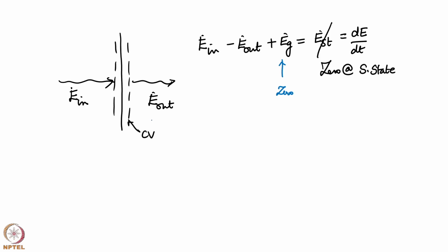How is heat coming in? This is the surface of the brick wall. There is an inner surface, there is an outer surface. Through this, energy is coming from Ts1 to surface S2 by conduction. So, the mechanism is conduction here, and energy is going out by convection. So, E dot in is equal to minus k A s dT by dx.